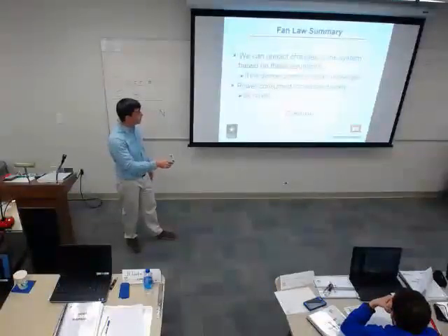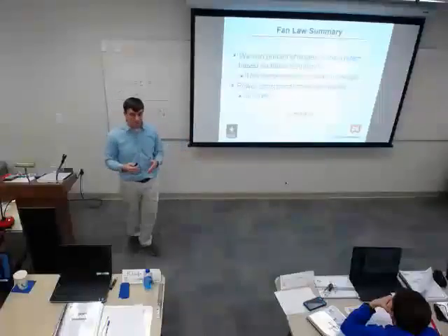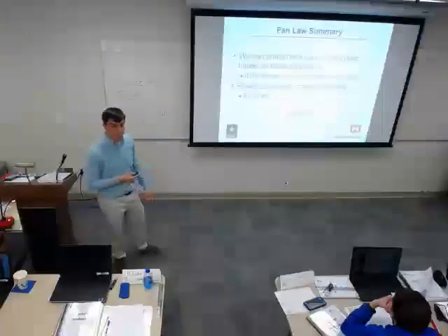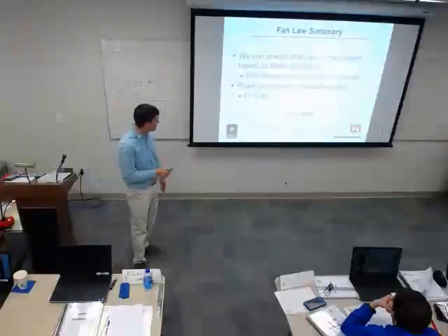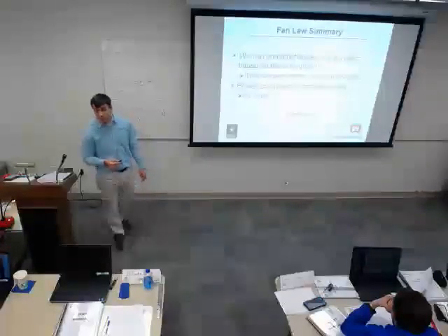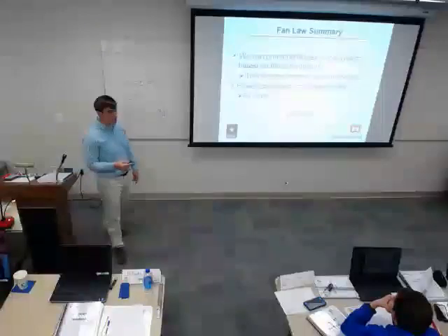Again, damper positions can't change. In a VAV system, dampers modulate all the time, so I never have a set system curve unless I go in and lock those damper positions down. Big takeaway, power gets consumed quickly. That cubic relationship can really hurt you. Questions? Fan loss?